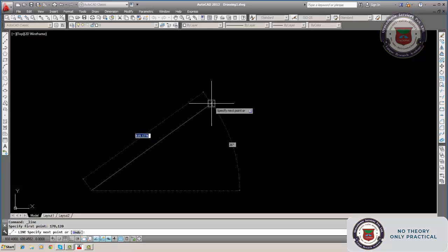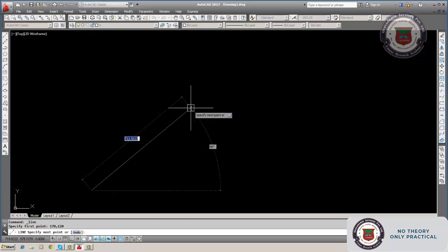So these two things give us the length of the line and the angle of the line with the x-axis. See this dotted line with this angle. We have already defined the angle measuring from east, and clockwise direction is positive.